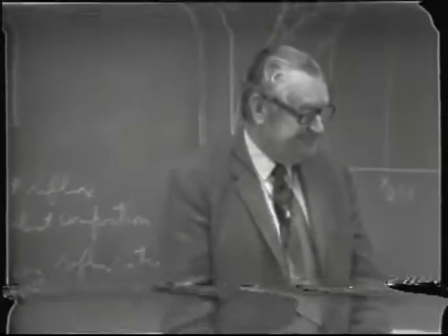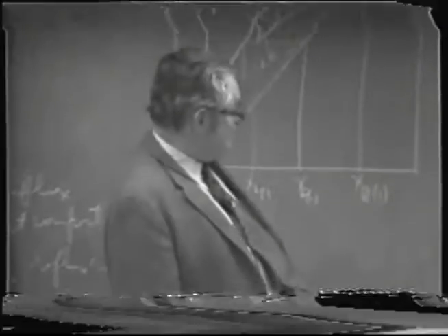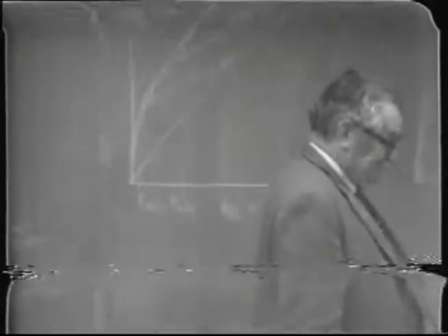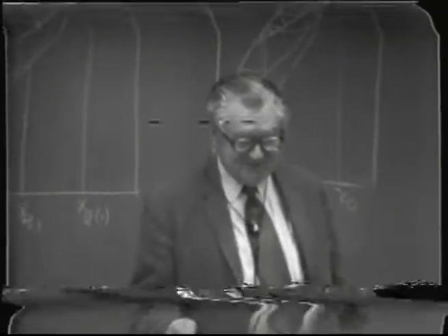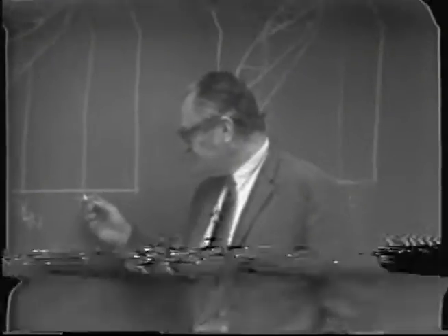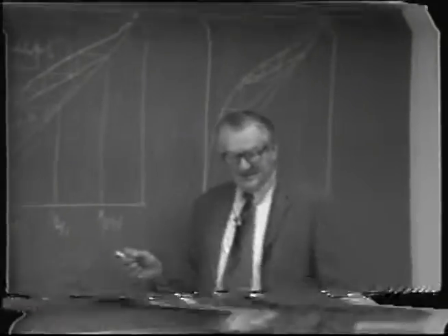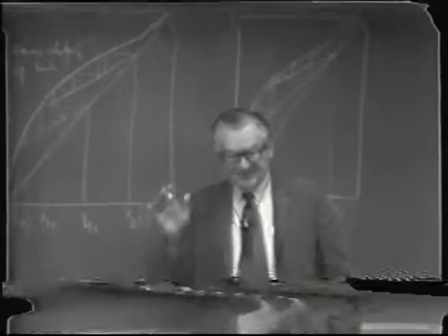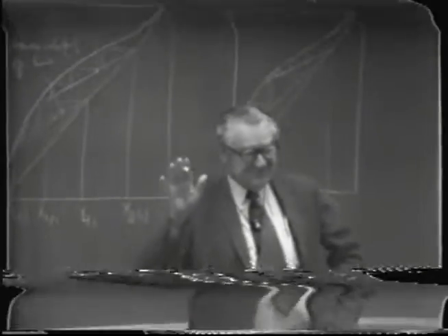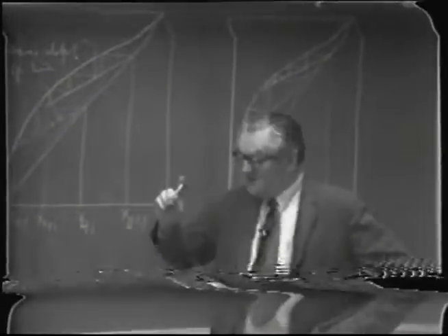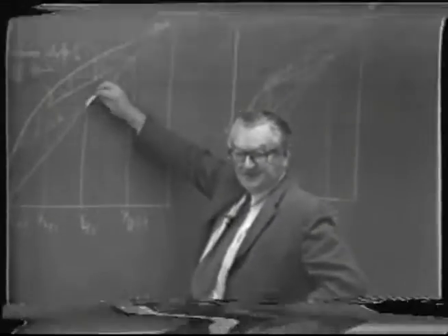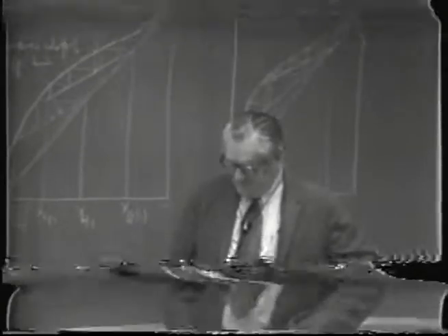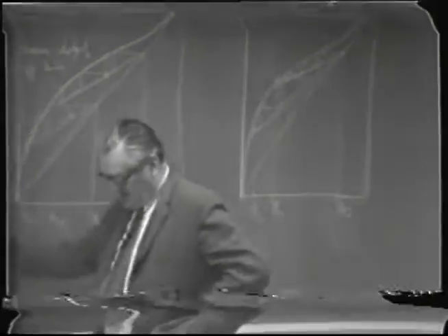So if I ask you the question, what is the minimum concentration of alcohol in the pot in order to produce a given distillate, with, let's say, 3 or 4 or some specified number of ideal stages, you take the number of steps between the curve and the diagonal. That'd be the minimum value.